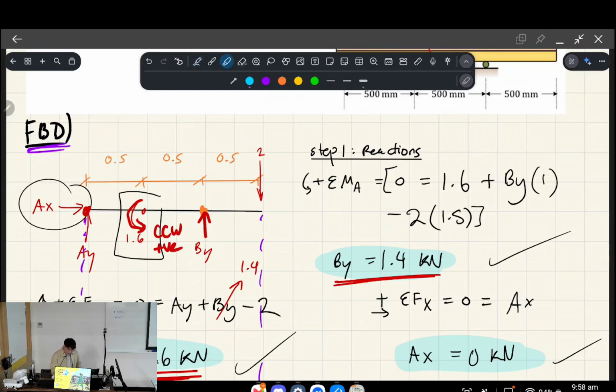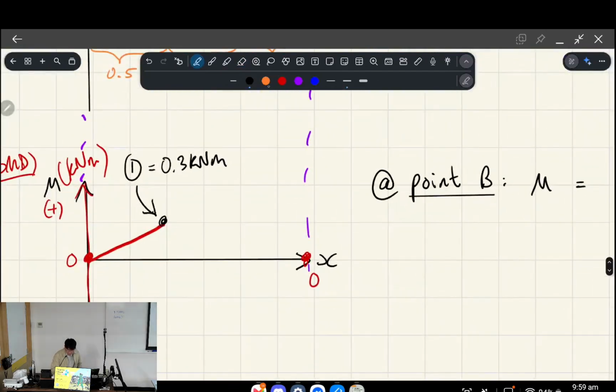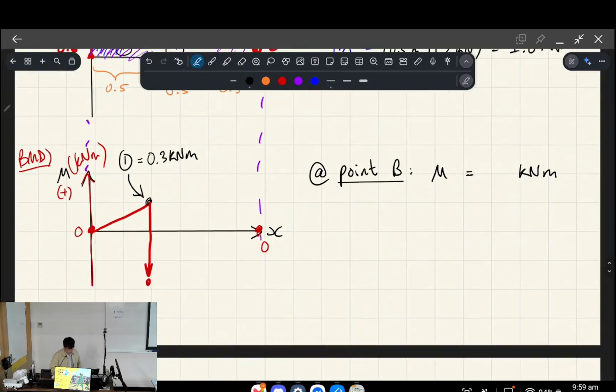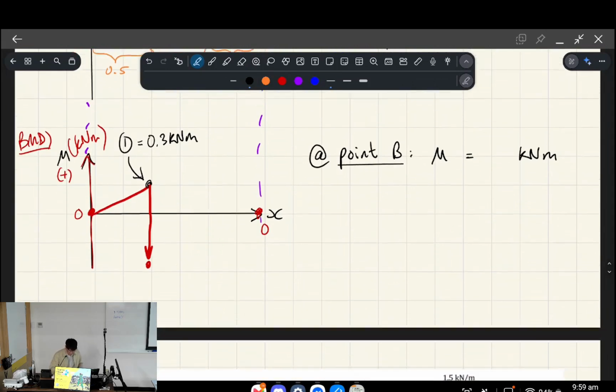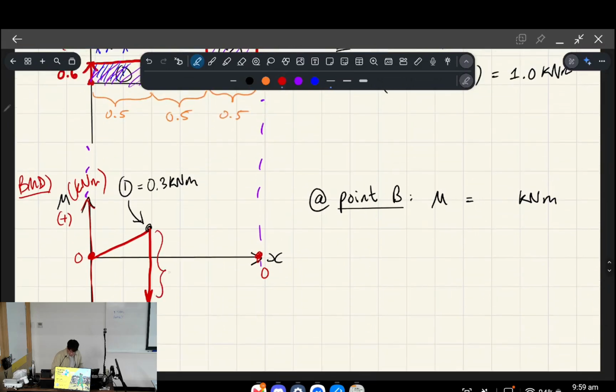But on a bending moment graph, a counterclockwise spin doesn't actually bring you up, right, as a discontinuity. It actually jumps you down, okay? This will make more sense when I show you the algebraic method, but just keep this in mind for now. So counterclockwise actually results in negative internal moment, right? Discontinuity that's negative.